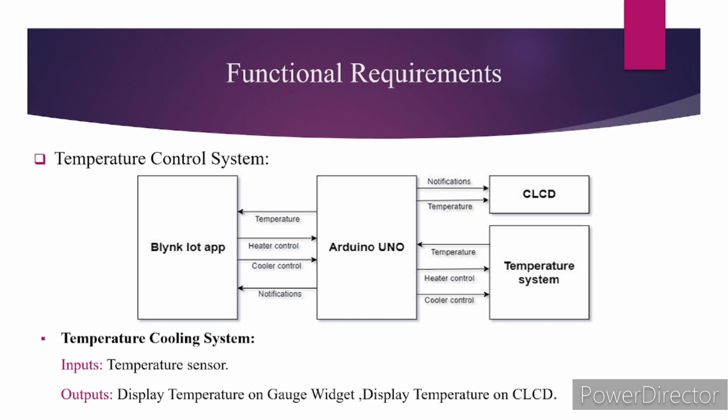Temperature sensor is used as an input to send the temperature details of our home to the Arduino. Then based on the values we are going to use heater and cooler accordingly. We have to create cooler pin, heater pin, and temperature widgets on the IoT app for controlling temperature using the app.